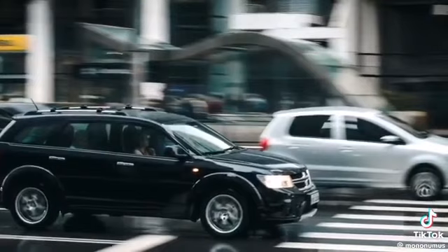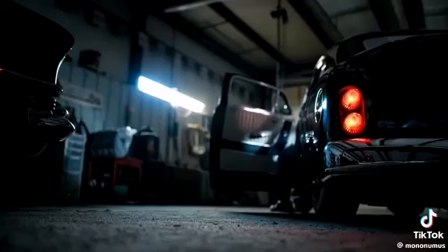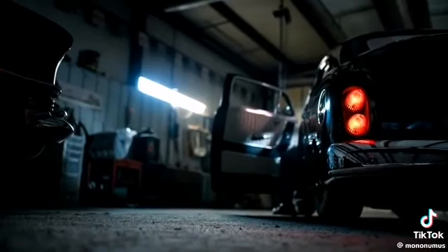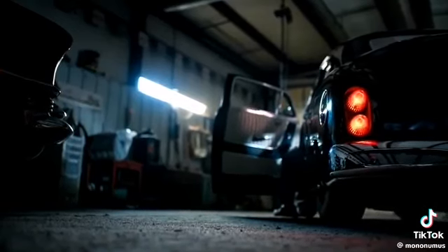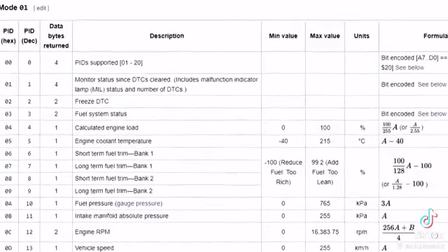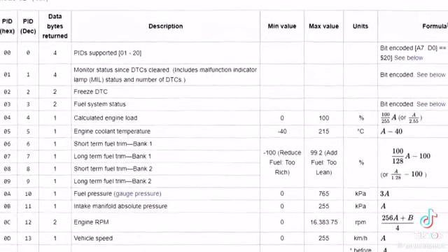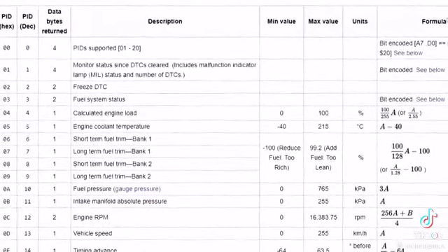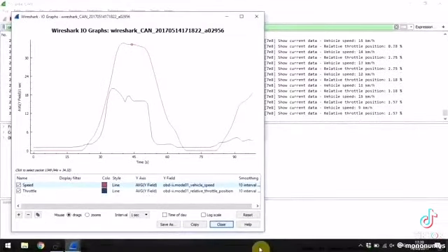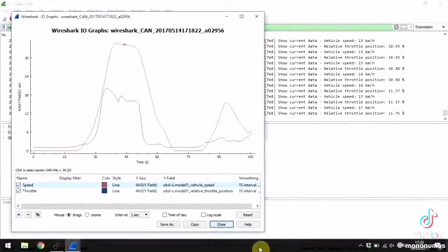And why should I care about OBD2? If you're here, you want data. Mechanics obviously care about the diagnostic trouble codes. Maybe you do too, while regulatory entities care about the emission data. But OBD2 actually includes a fairly broad range of standardized parameter IDs, PIDs, that can be extracted across most regular automotives. This means that you can, for example, get human-readable live OBD2 data from your car on some key parameters, which is pretty cool.